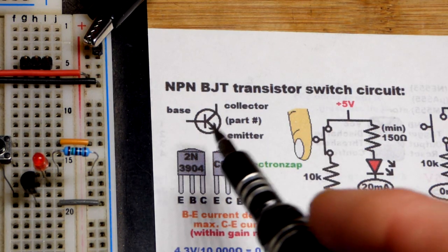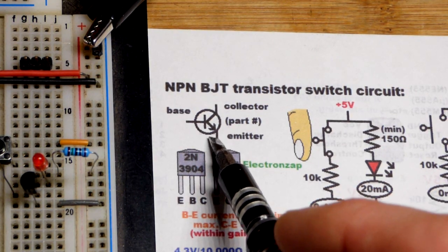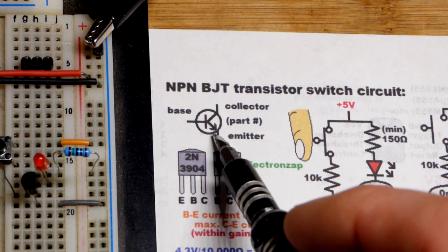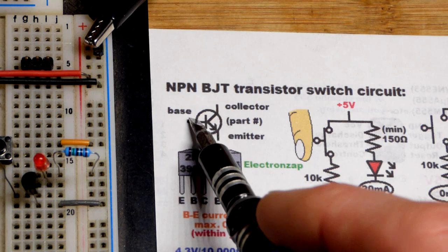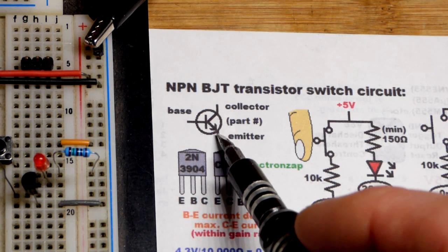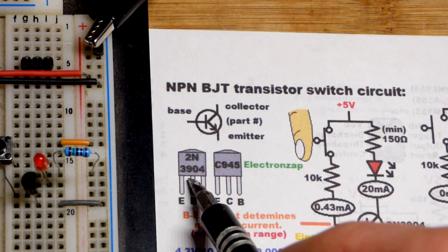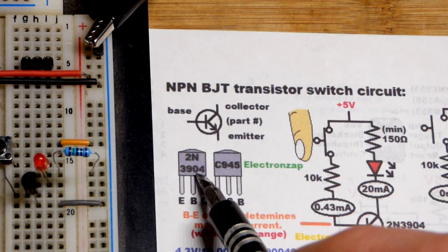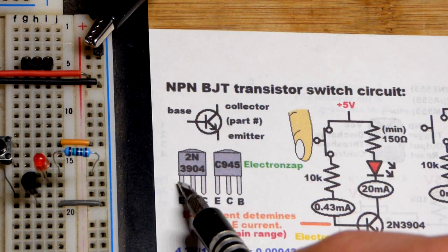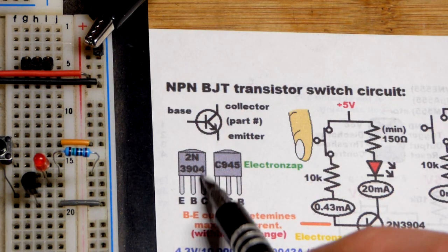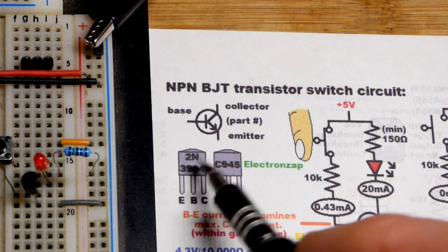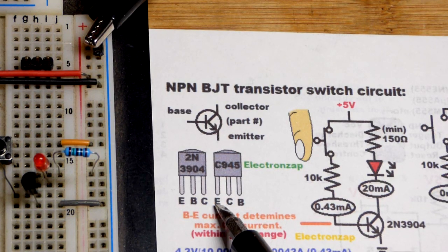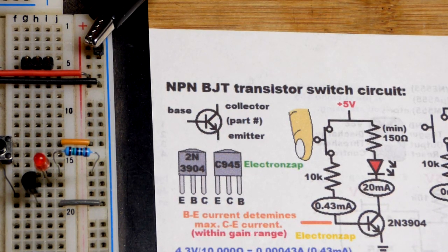So now, when you see an NPN bipolar junction transistor schematic symbol, it may not be circled though, and usually it's not named. Pins are not usually named. But in any case, we got collector up there, base over there, emitter over there, and you got to match that with the physical component you're using. Maybe there's a part number, but whether there is or not, use the part number that you got, 2N3904. We got emitter on the left, base in the middle, and collector on the right when you're looking at the front. If you're using a different transistor, it may have a different pin layout. This one has emitter on the left, collector in the middle, and base on the right.